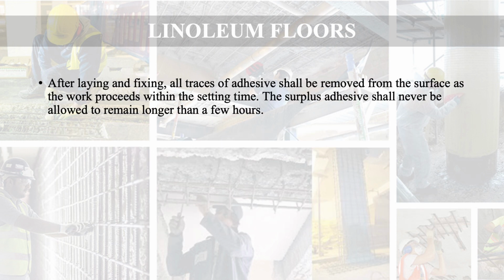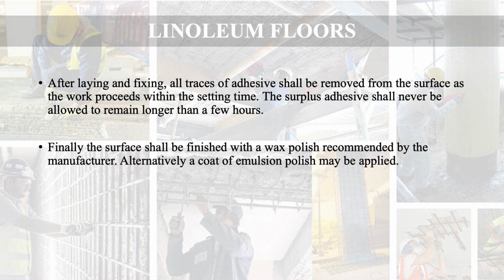After laying and fixing, all traces of adhesive shall be removed from the surface as the work proceeds within the setting time. The surplus adhesive shall never be allowed to remain longer than a few hours. Finally, the surface shall be finished with a wax polish recommended by the manufacturer. Alternatively, a coat of emulsion polish may also be applied.